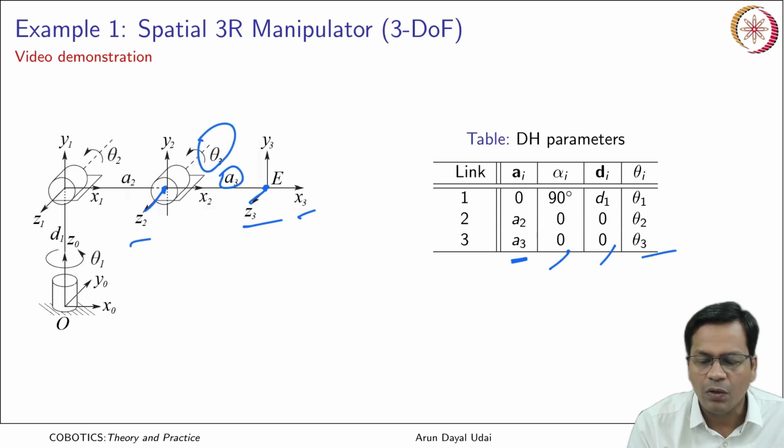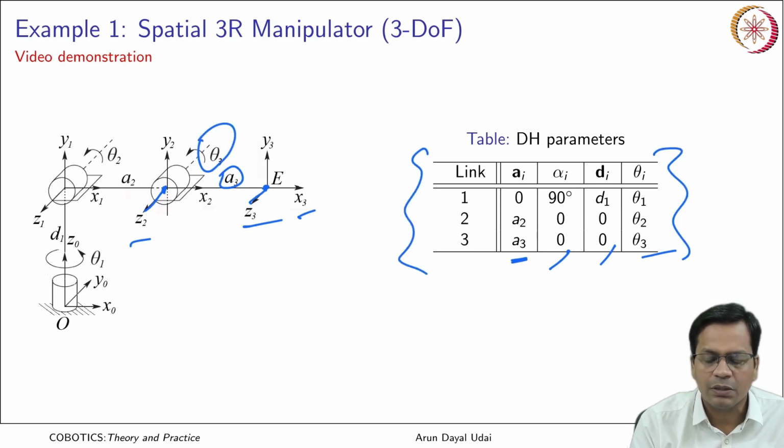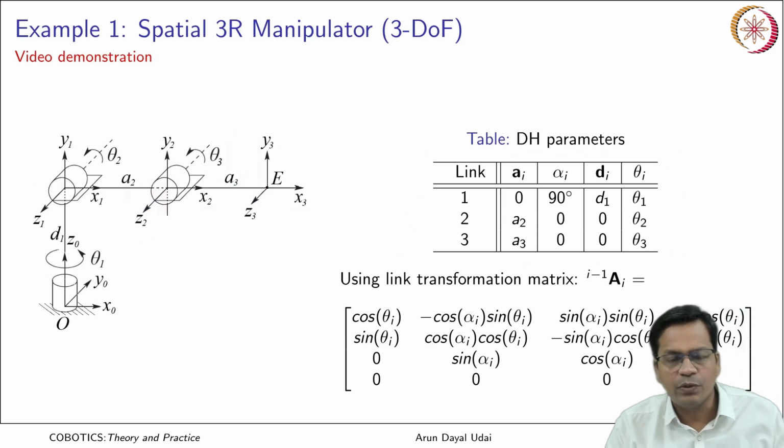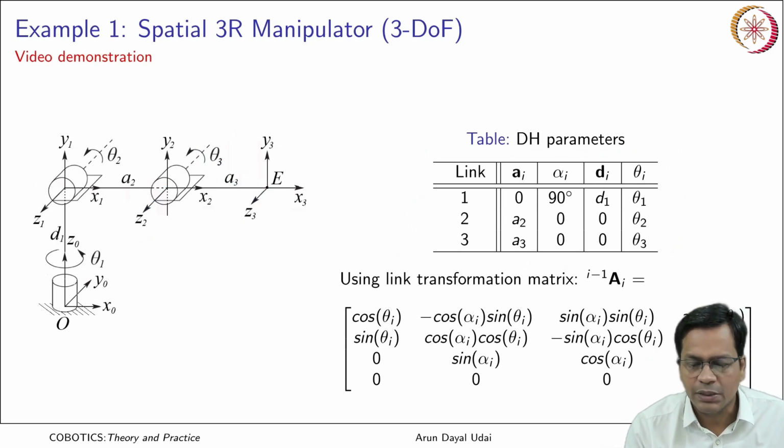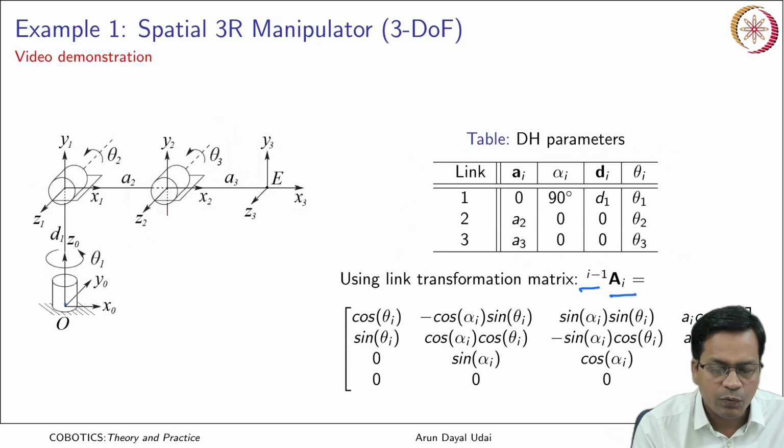Okay. So this is how the whole set of DH parameters is complete, and we tabulated it in a DH parameter table. Okay. So we will use the link transformation matrix here, A i minus 1 i, that will take you from this to this. So A10 would mean it is taking you from the 0th to the 1st frame.